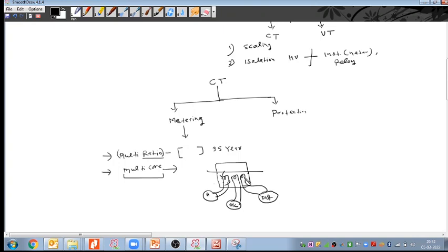It is possible because all cores are separate from each other. So we are doing core selection and sizing calculations when we talk about CT sizing calculations. Sometimes this is called core dimensioning. Sometimes in the CT sizing calculations, Excel sheet or calculation document, we write core dimensioning calculations. That statement is also correct.